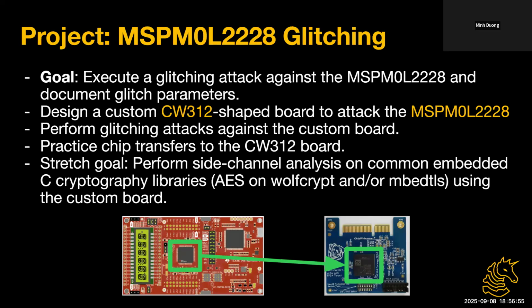There's code that every time it senses something external, it just fries itself. That's actually a rule. You're not allowed to do that. They thought of that. In particular, the kind of mitigation you're describing, monitoring the voltage line, is actually very difficult, because these glitches run for a very short period of time. Whatever mechanism is triggering that is also slow, and it's liable to not execute correctly in the case of a voltage injection attack.